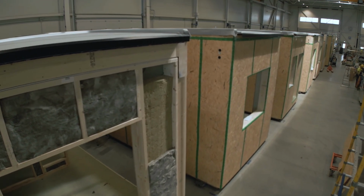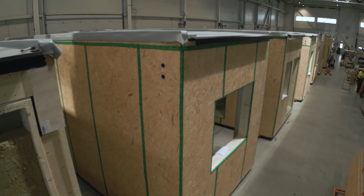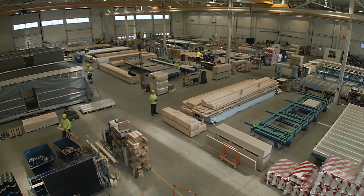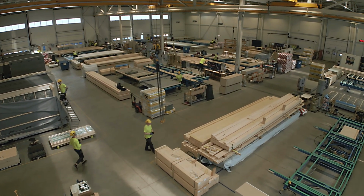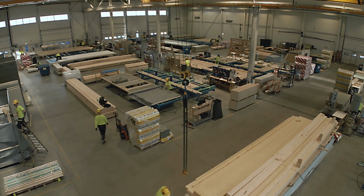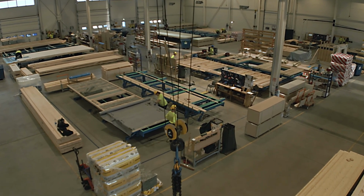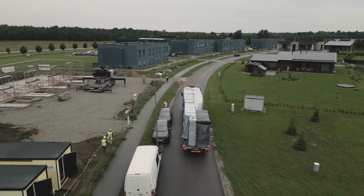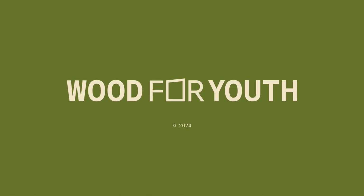As well, factory quality control is more systematic and thorough than on-site inspections. And finally, in the case of a solution based on a wooden frame, less energy is consumed and less carbon dioxide is released into the atmosphere. This is due to the weight of wooden structures. The lighter and slimmer the building, the less carbon dioxide is released into the air during the production process, during the transportation of materials and final products, and during the construction of foundations.